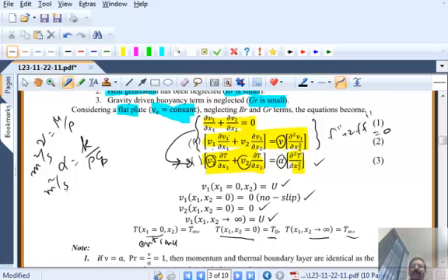If I make alpha equal to nu, what do you think would happen to the delta T and delta, thermal and momentum boundary layers? Why do you say that? The equations look identical, right? If I replace alpha with nu and V1 with T, I don't see the difference. Okay, so the solution must be exactly the same.